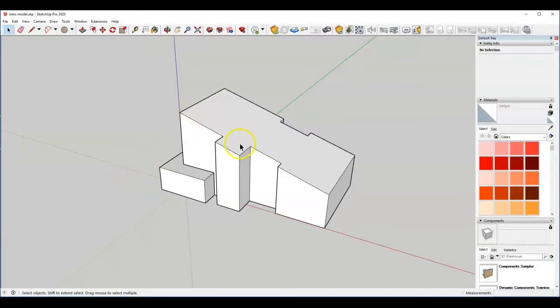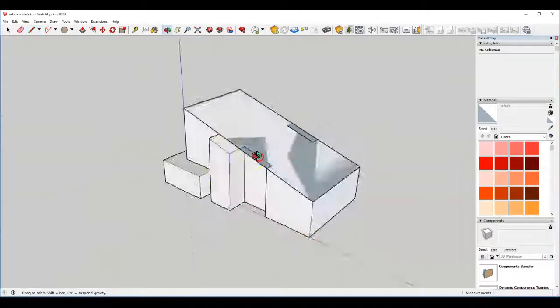Ultimately, for this main roof, we're just going to do the same things we did before. We're going to draw a rectangle, we're going to push and pull. That's most of what SketchUp is, especially in the design phase. So I'm going to come here and come back to my line tool. And since my current objects are already groups, I'm just going to retrace over the primary rectangle that is the roof in this case. So I get this shape.